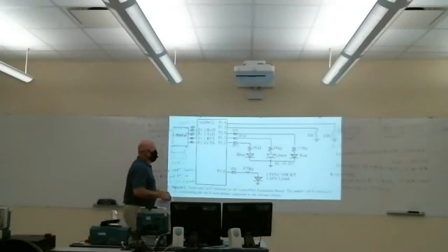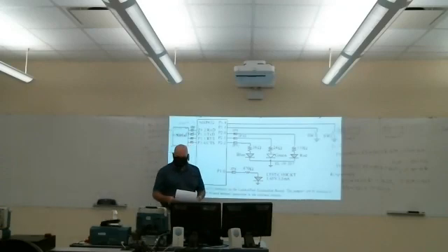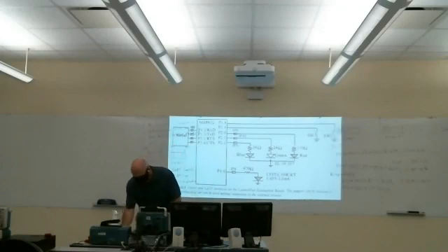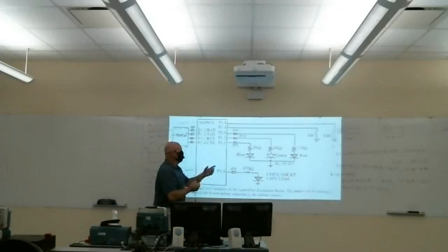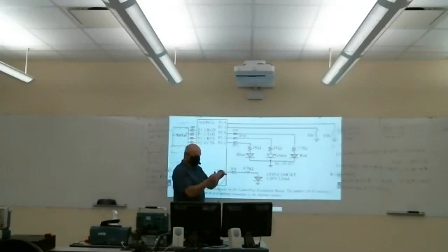If you notice, on your board, you have these various jumpers. Okay, so you can remove these jumpers which connect two pins. So it's essentially creating an open circuit. So if you remove this jumper 11, which is down here at the bottom of the board next to the blue LED, you're going to break this connection between that port pin and this blue LED.